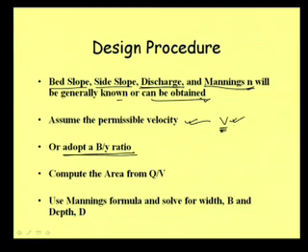And then once we have this V and discharge, we can compute the area. So this area is known. Then we can use Manning's formula and solve for the width B and depth Y, because design of a channel means we need to know the bed width and the depth of the channel.